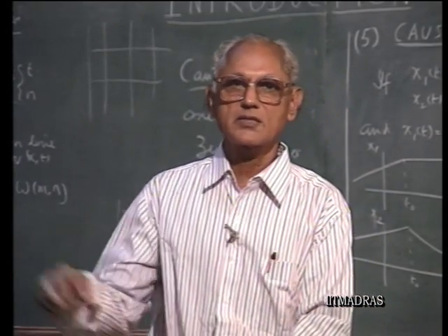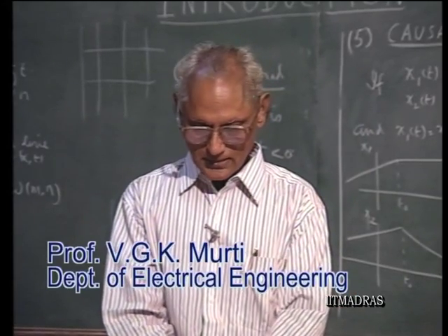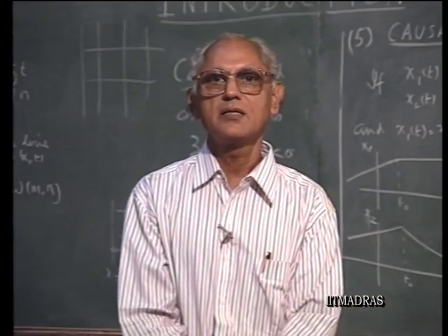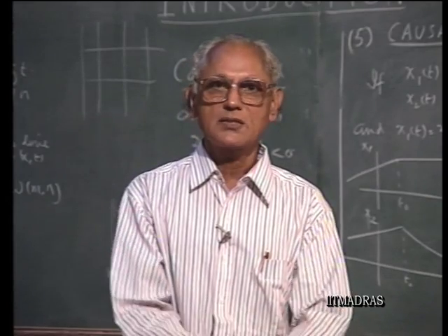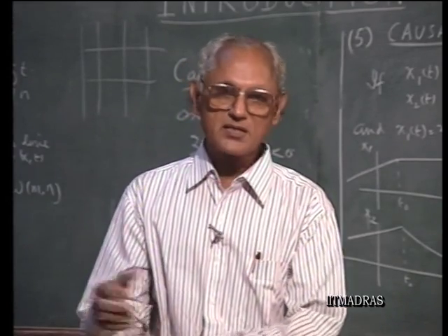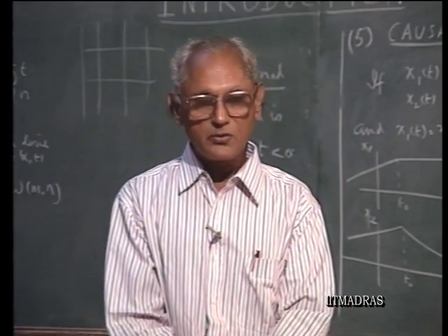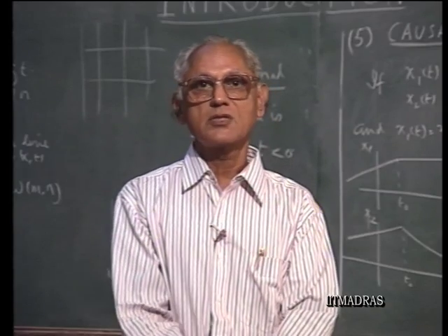The analogous electrical circuit for a given mechanical system is set up, and you analyze this electrical system with all the gamut of techniques that are available for electrical circuit analysis, and once you have that, you translate the results back to the original domain, interpret the results suitably, and then you get the solution for the non-electrical system. For experimentation also this is convenient.